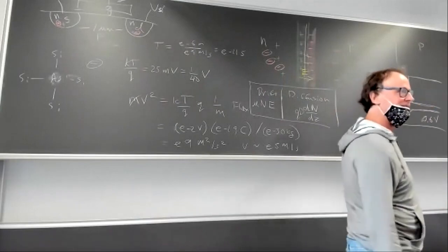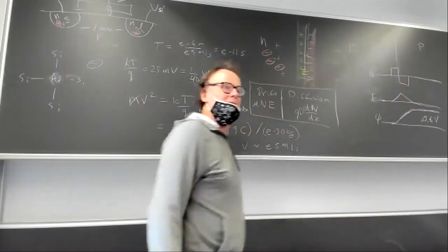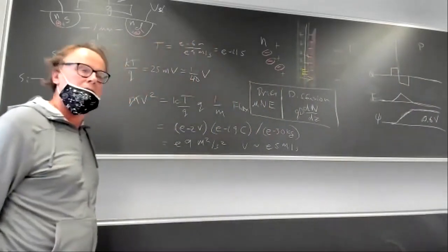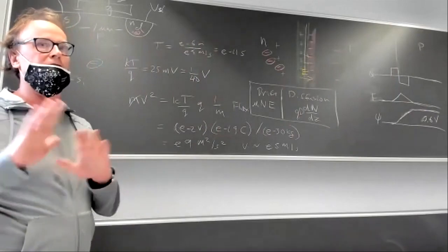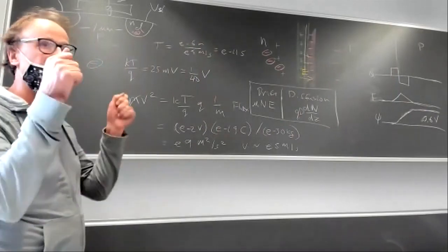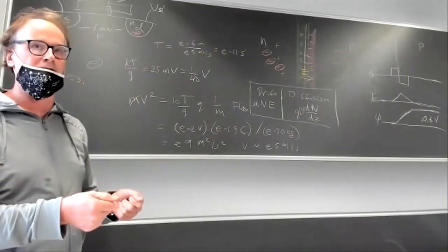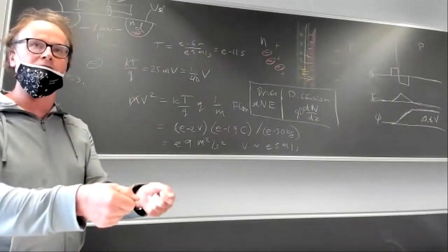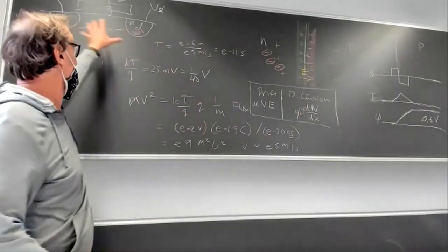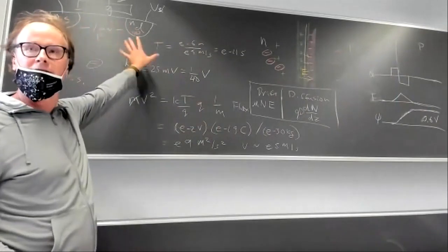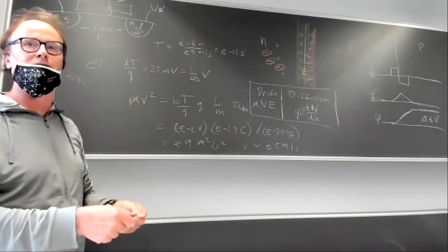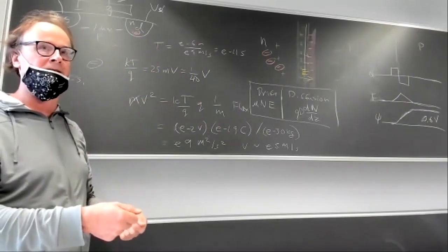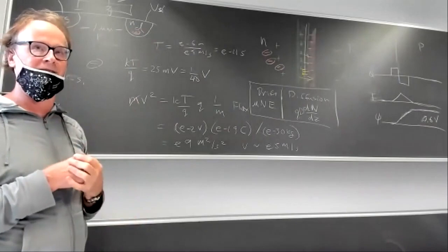I see. Okay. So it's net work, just in general. It's not the actual potential difference. You can't measure this potential difference. This is another confusing thing. You can't stick a voltmeter on there and measure this potential difference, because when you stick the metal electrodes on there, they also have their own junction characteristics, even though they're not junctions. So it turns out that you won't measure any voltage if you just stick a voltmeter on there. But there is an electric field in there, right?